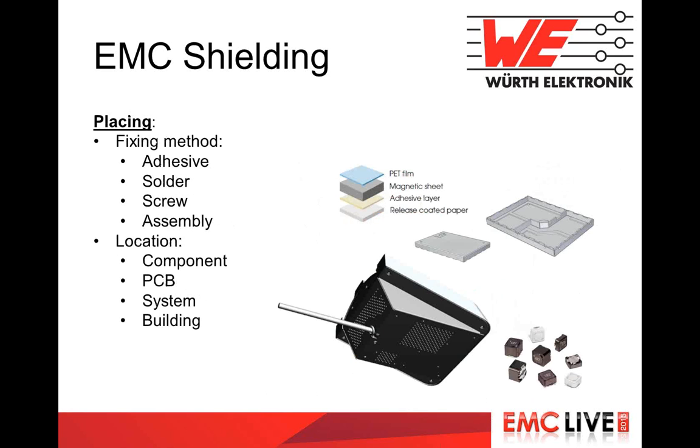By placing, we understand the fixing method. This is quite important for shielding. We can use adhesive, we can solder the shield and screw it, or just assemble it. And depending on the correct use of the fixing method, the shield will be more or less effective and it will last longer in time.